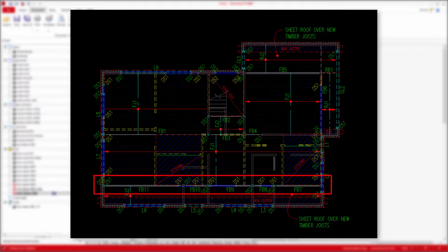Having a look at our remaining beams, they're all going to be fairly straightforward. Each of these beams will be loaded with floor, lower roof, upper external wall and upper roof. Although a few of these have columns coming from above, as the spans of these upper lintels aren't too large, you can probably justify just idealizing these loads into a UDL across the entire span. We'll then skip ahead to the end of our floor beam designs.